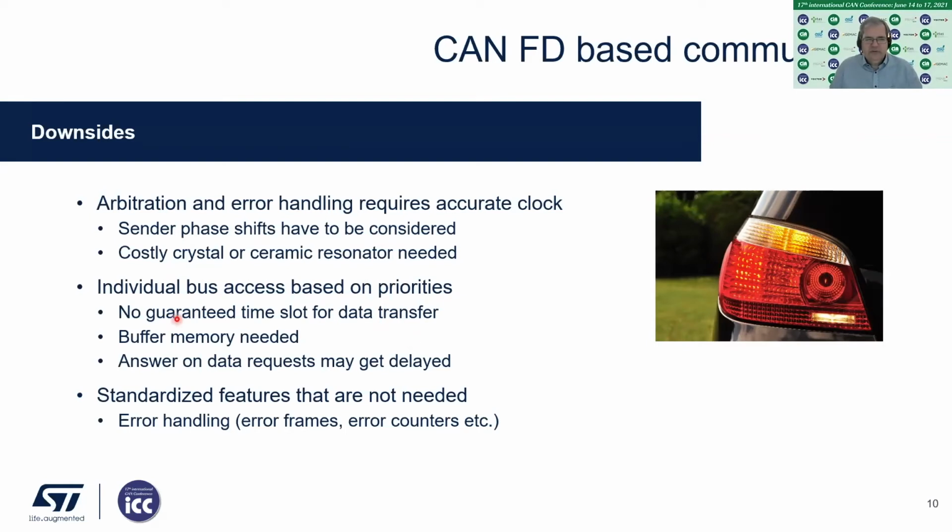So that means there's not really a guaranteed time slot for the data transfer. We need buffer memory, which is in these small devices also quite expensive. And anyway, an answer to a data request may get delayed, and you maybe cannot really rely on a certain command sequence to drive your animations for these LED drivers. And then there are additional standardization features that need to be implemented and that we do not need. For example, the error handling with the error frames and error counters that are not required in such a commander-responder scheme, as I indicated previously.